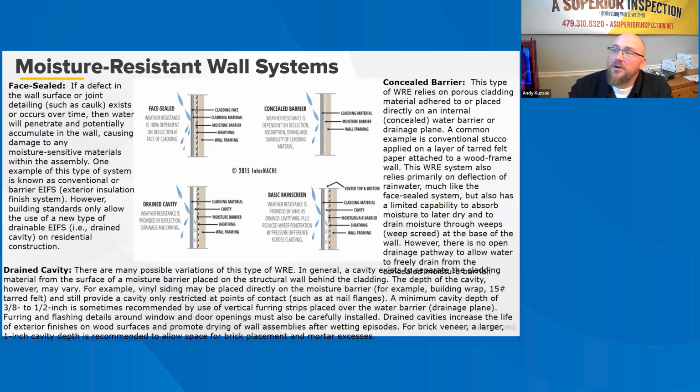All right, so residential code 703, exterior covering. What is a weather-resistant exterior wall envelope, or a WRE? This section discusses what a home inspector should look for with weather-resistant wall envelopes, which can include siding, water barriers, etc. Current U.S. building codes don't distinguish between the inherent performance differences of the various weather-resistant envelope systems.